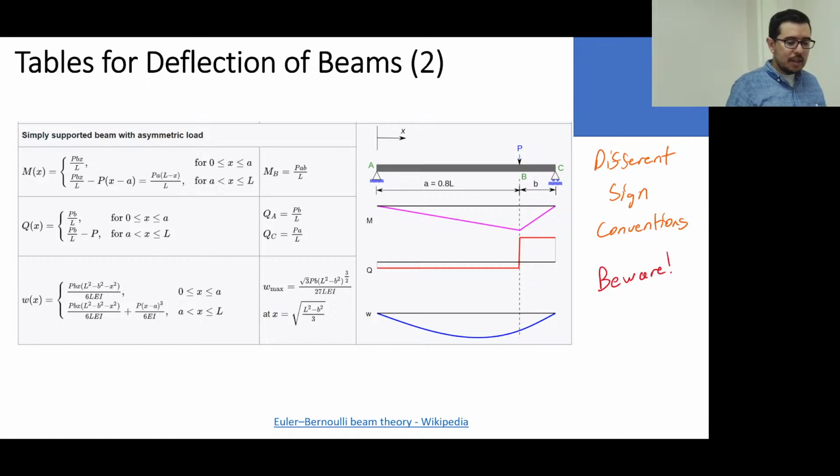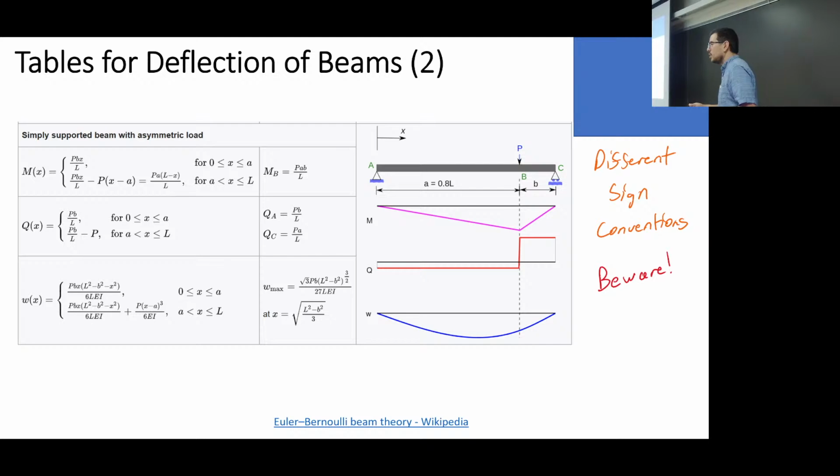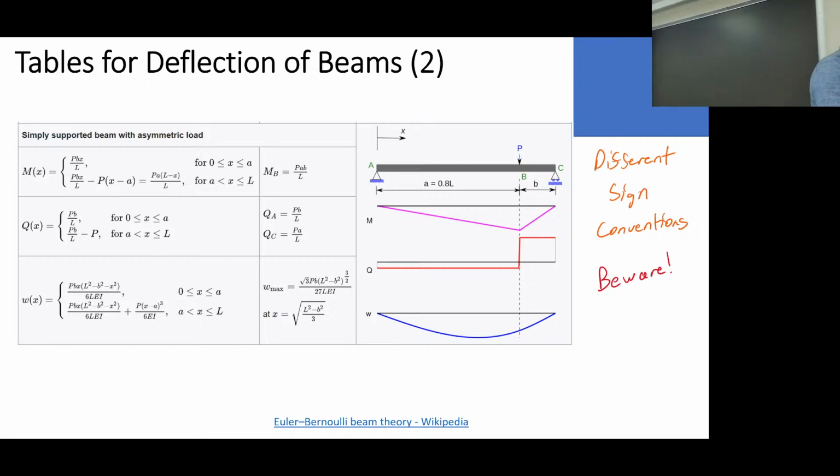And if I know what P is, I could go back and plug that P into an equation to figure out what the moment is. And if I know what the moment is, then I can figure out what the stress is. So you can use these relationships, the displacement at a given location, to back calculate what the stress is based on the curvature or based on the displacement you might see. Does that make sense? Okay, so that's kind of working backward.